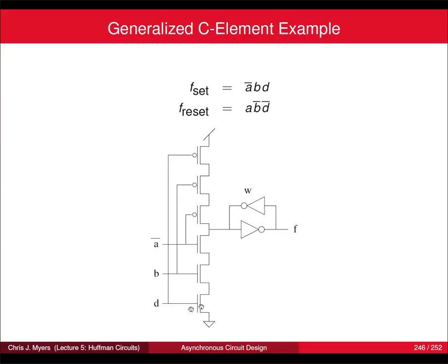That makes sense? So you can see it's much more compact, but most gate libraries don't have these in their gate libraries. So that's the downside, right? You're going to either have to custom design it yourself, or you're going to need to use some auto layout tool to try to build these gates for you. But the advantage is it's smaller and faster.